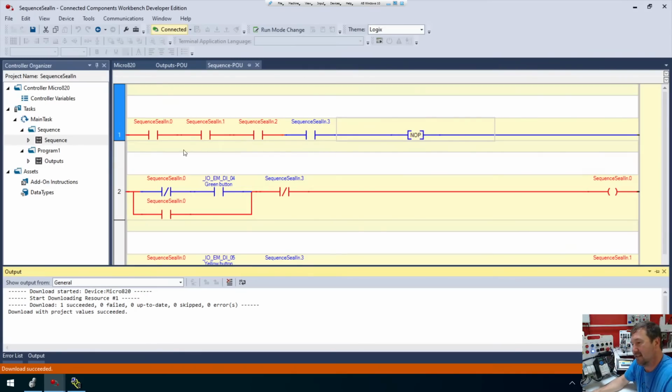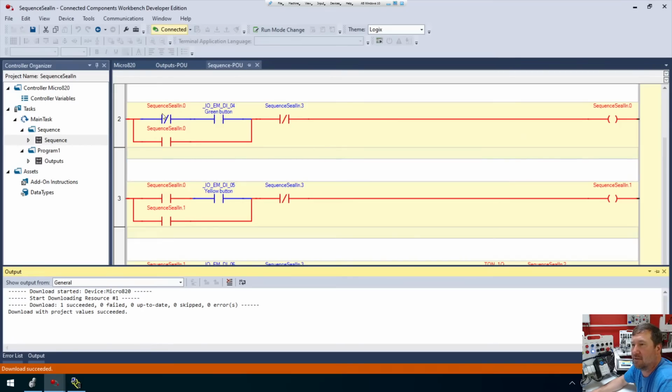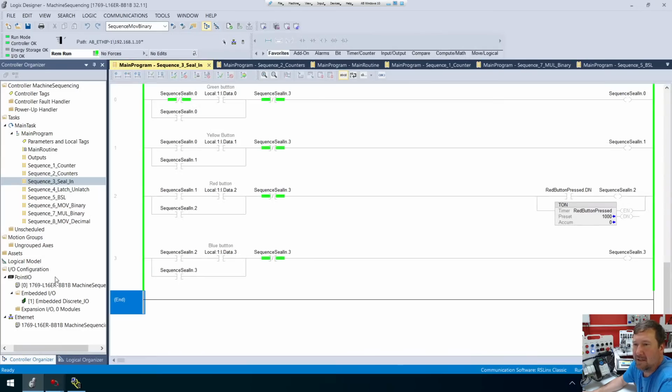And this is similar to what I did in my first program, but I think I left a lot of opportunities out for troubleshooting. And also, it really becomes a bear if I want to insert another instruction in the middle. Mainly because to do it, I have to shift all these down, and I'm not going to do that. I'm going to end up adding some crazy oddball bit in here to add another step in. So overall, I don't think that the seal in is a good way to do it. So I'm going to leave that at that.